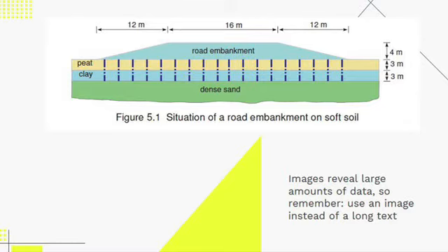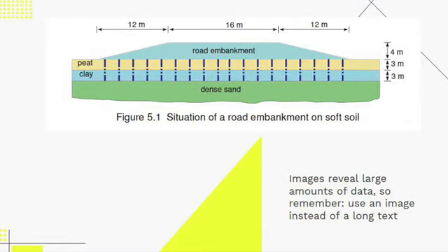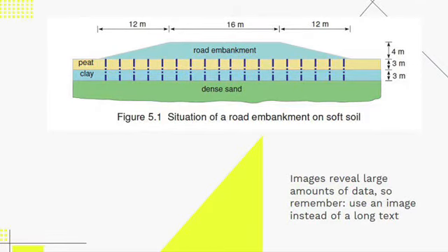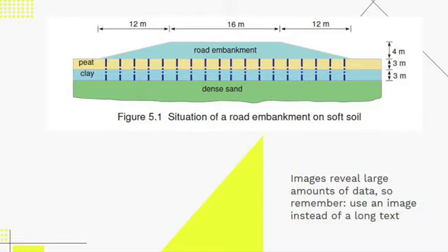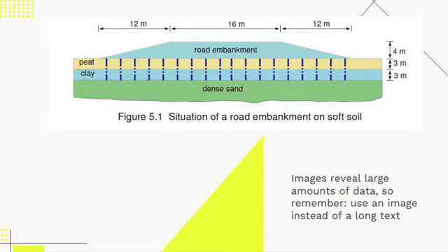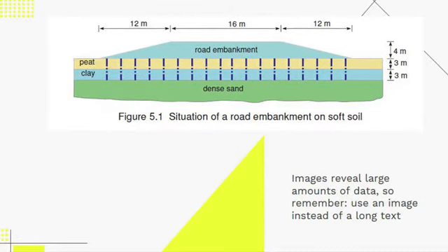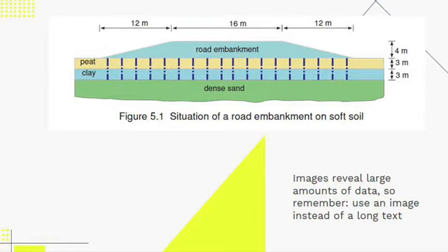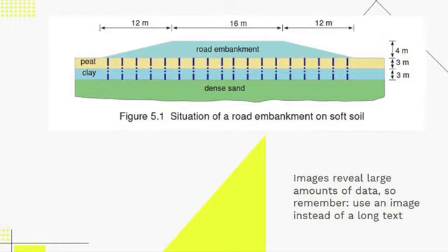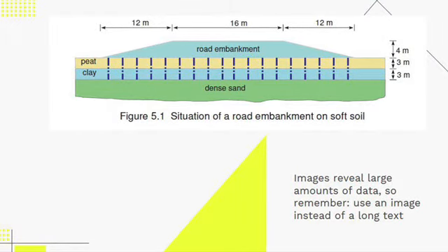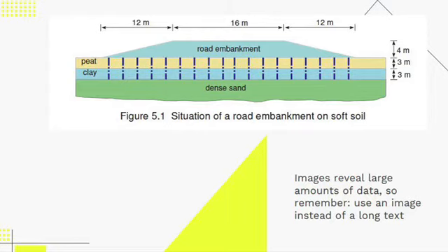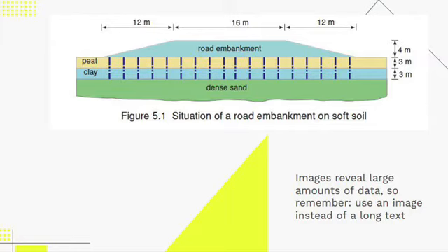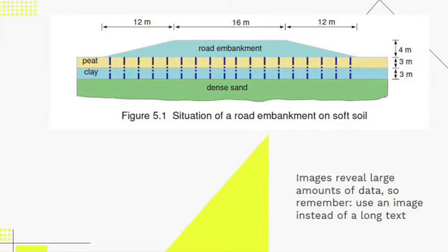For the first step, input the general settings, such as making sure that the model is set to plane strain and the element is set to 15 node, and also define the limits for the soil contour. Okay, the next one is to define the soil stratigraphy, create the borehole, and also create the water level, which is located at y equal to -1 meter, and the borehole column specified at the value of -1 head.